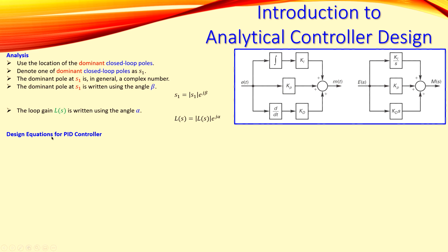So let's first look briefly at what a PID controller is. We have the P controller branch, which is just a linear amplification. You have the integral part, the integration, and associated with that its own gain. And we have the derivative branch, with its associated gain. If you combine these three branches together, you have the classical PID controller. Now this is in the time domain.